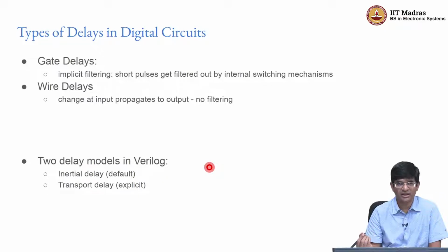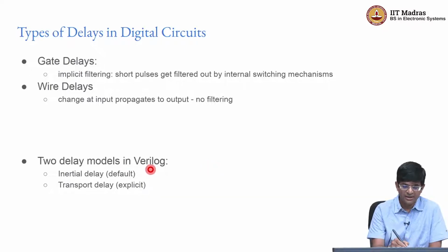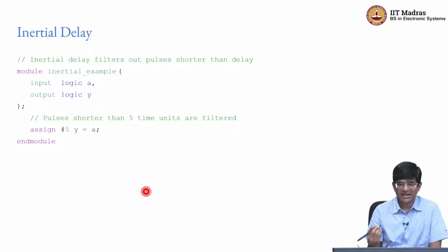You have certain hardware and you want to be able to model it, which means that unless you are a designer who is trying to provide a model of your code to someone else for simulation, you should not normally be looking into this level of detail on how delays are modeled. Okay. Having said that, there are a couple of concepts that are important to at least keep in mind. There is the notion of inertial delay and transport delay, right? And a couple of examples will probably help to illustrate that a little bit better.